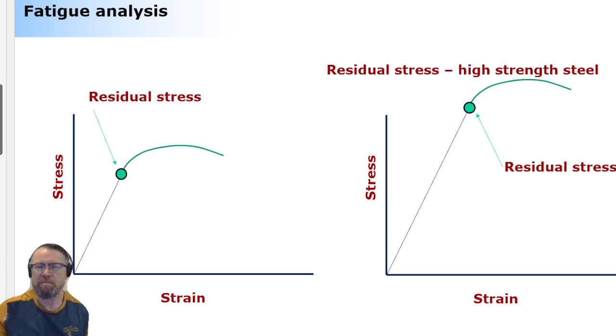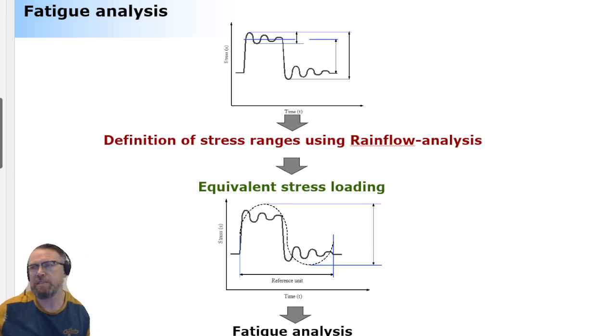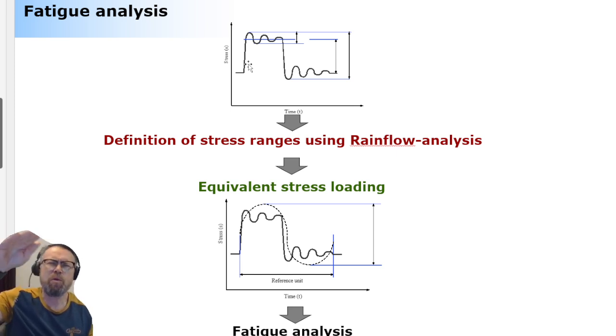Okay, now let's just think that we are capable of getting the stress history using the technique that I just explained in the first part of my lecture, so you can get it. And the stress history, once it is in your use, what should you do with that? Well, what you should do with that is this: you should calculate the stress ranges, deltas of stresses, because what matters in fatigue is not so much where the level of stresses is that they're traveling. Most importantly, if you take stresses on and off, this is something that is very, very dangerous in terms of fatigue.